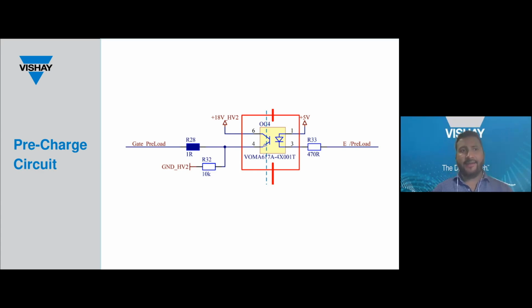Since the gate drive signal from the microprocessor to the pre-charge MOSFET must cross the isolation barrier that we were mentioning, we need to select a component for galvanic isolation. Since this is just an enable signal, though, that switches at a relatively low frequency, we use another optocoupler with a phototransistor output. Again, you can see the red line indicating the isolation barrier.